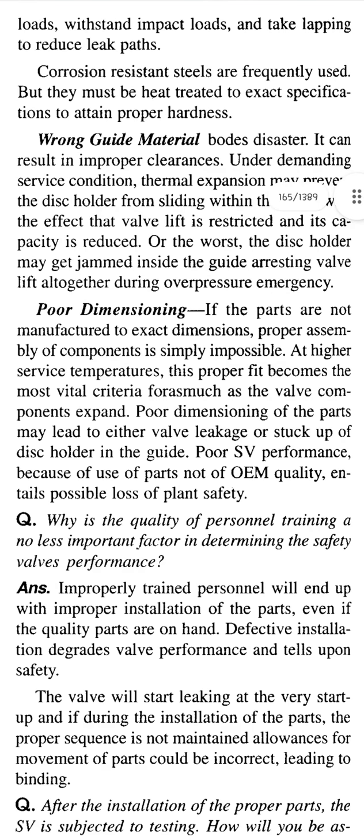Poor dimensions. If the parts are not manufactured to exact dimensions, proper assembly of components is simply impossible. At higher service temperatures, proper fit becomes the most vital criterion, as much as the valve components expand. Wrong dimensioning of the part may lead to either valve leakage or sticking of the disc holder in the guide. Poor SV performance because of the use of parts not of OEM quality entails possible loss of plant safety.